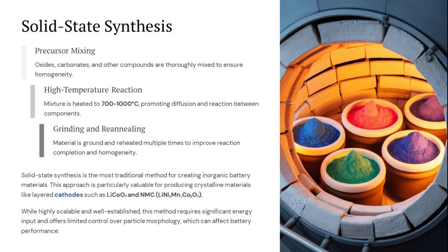Solid-state synthesis. The traditional approach to synthesizing many inorganic battery materials, particularly cathodes, is solid-state synthesis. This method involves mixing precursors, typically metal oxides, carbonates, or other salts, and heating them at high temperatures, often 600 to 1000 degrees Celsius, to promote diffusion and reaction.